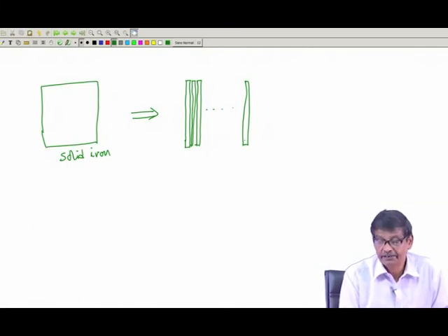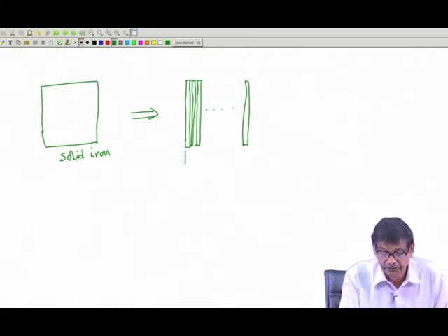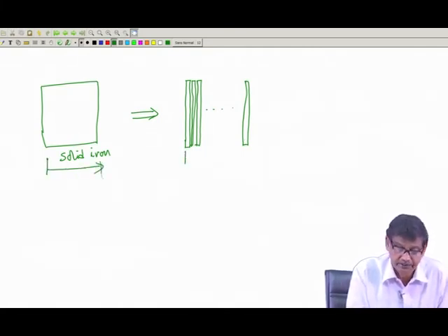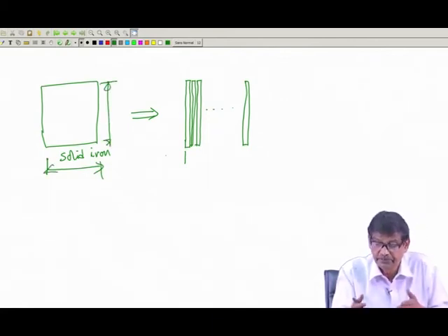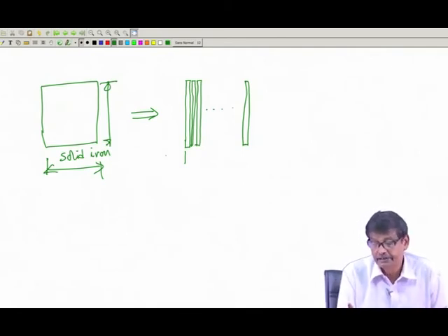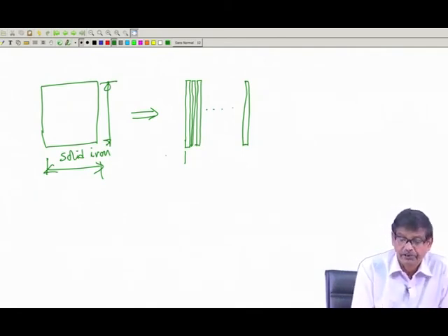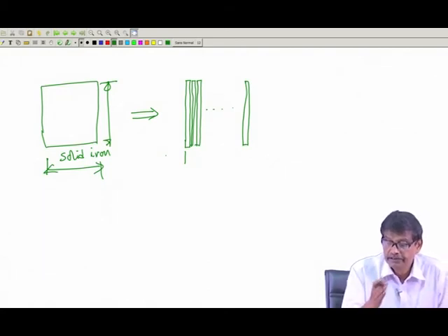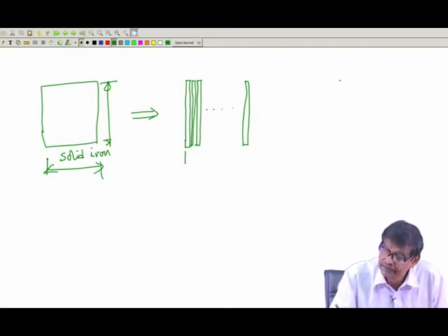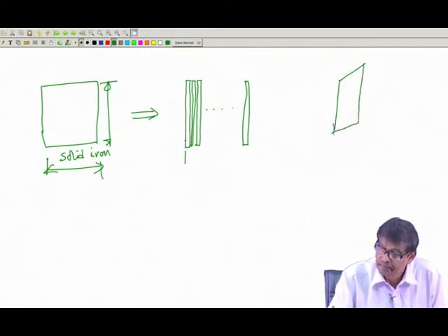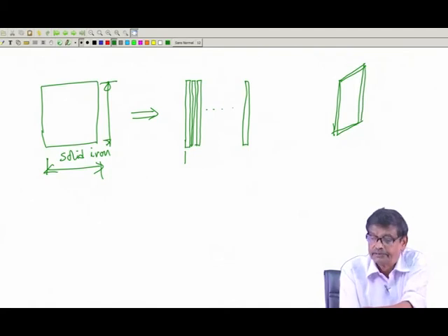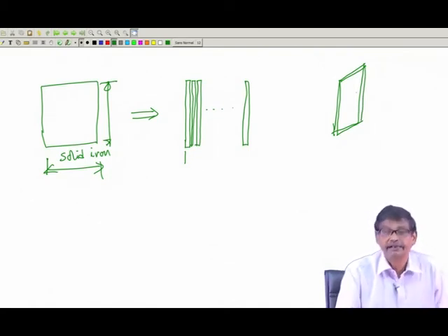Thickness of the book will be achieved. So this is the width of this iron, this was the length, whatever it is, sectional area. The same sectional area can be realized by, instead of using a solid block of iron, thinner plates. That is, you take one plate there, take another plate there, and stack them together, clamp them to get, I think you have got the idea.